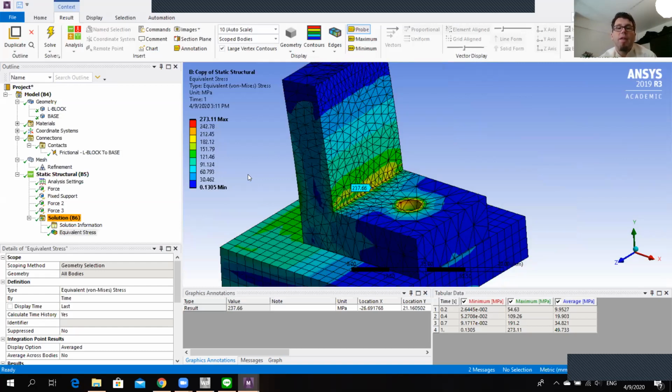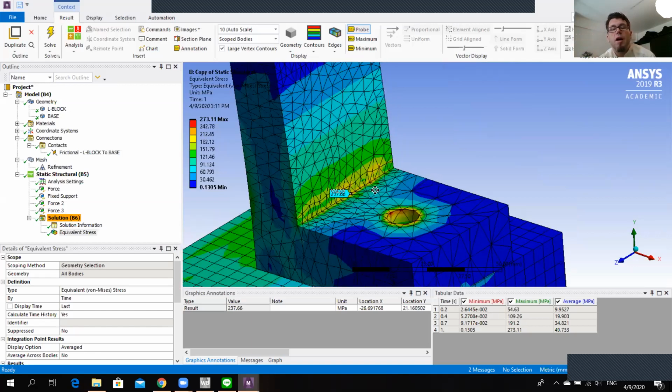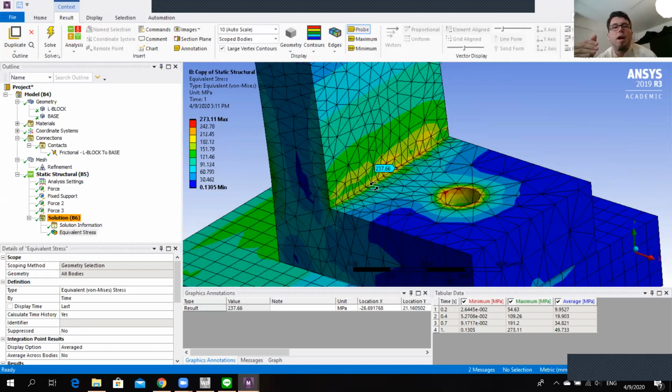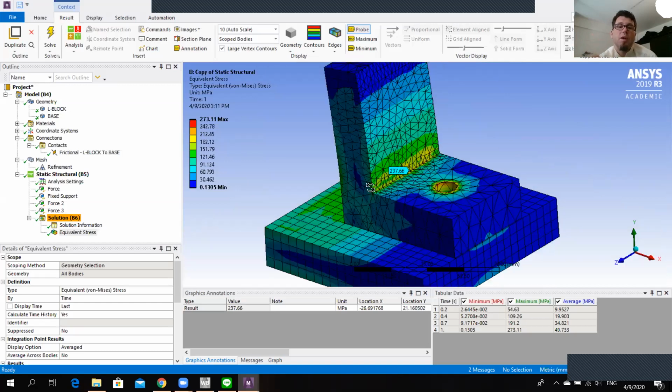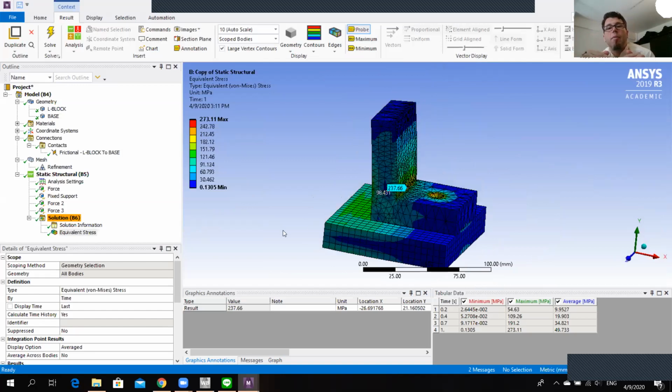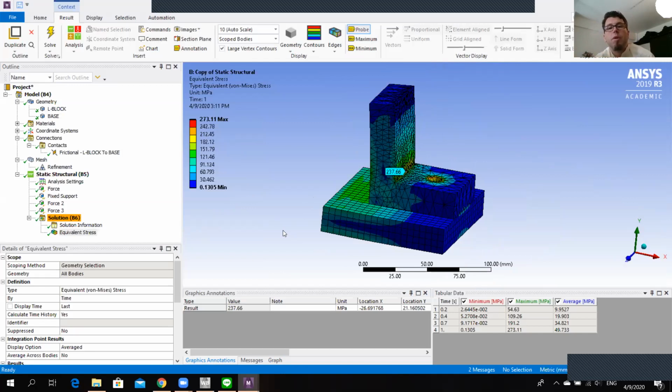So you can see the steel part. Can you zoom out so we can see the steel part a bit better too? You see von Mises stress. So obviously it's von Mises stress. If we would look at the maximum principal stress, it would be tensile stress on the bottom, compressive on the top. Here with von Mises, it's always a positive value, similar value going into the green region. So around 120 to 150 megapascal, pretty high stress level for the steel part, probably depending on the steel, under yield.